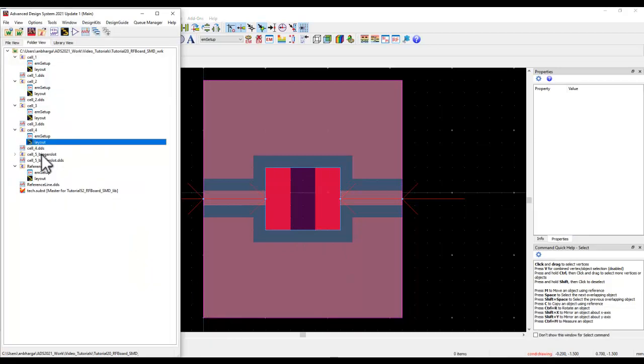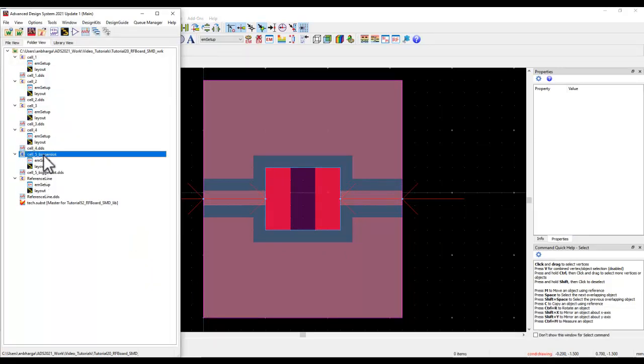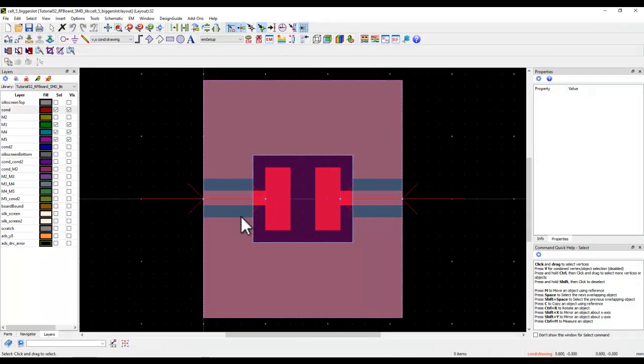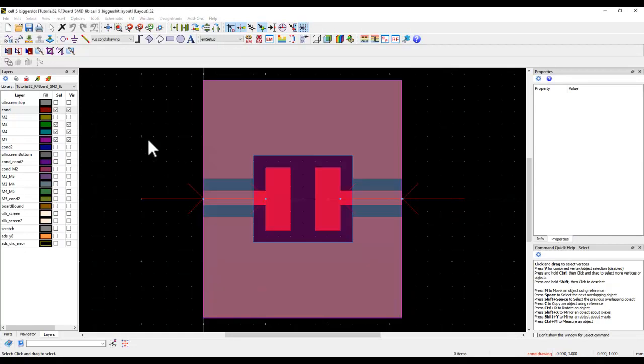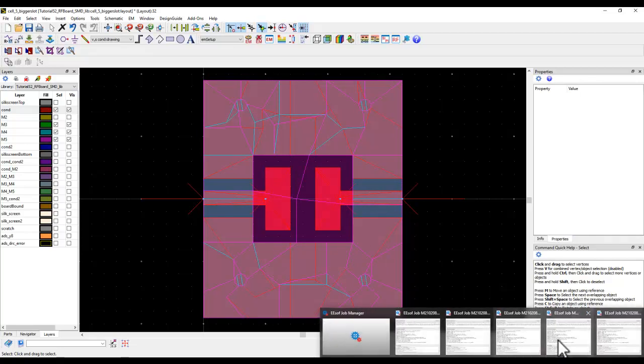However, if we provide a little bit of space, and that's what we call a bigger slot in my design context, so I increase the size of the slot a little bit more around this pad area, and if you simulate this particular design, we will achieve our objective because now the fields have sufficient place to distribute along this capacitive region or the low impedance region, and now we would be able to fulfill the criteria which we are looking at.